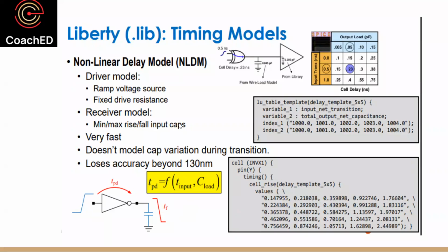Okay, so let me try. Propagation delays are varied. Okay, so Sharon, do you want to unmute yourself and describe what you mean by that? Yeah, sir. So in a circuit, we'll be having different parameters. If my transistor is connected to resistance, there will be a different propagation delay. If it is connected to a capacitor, then again I'll have a different propagation delay. And if it is connected to a wire and different types of metals also, I'll have a different propagation delay.